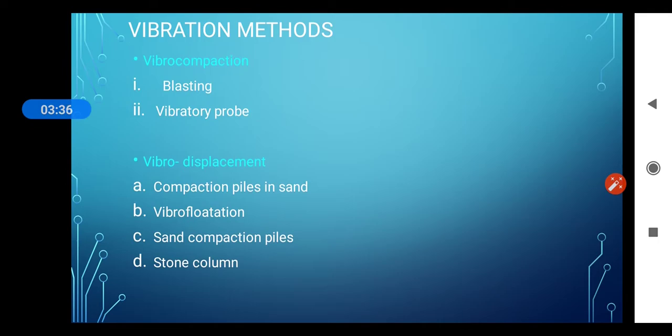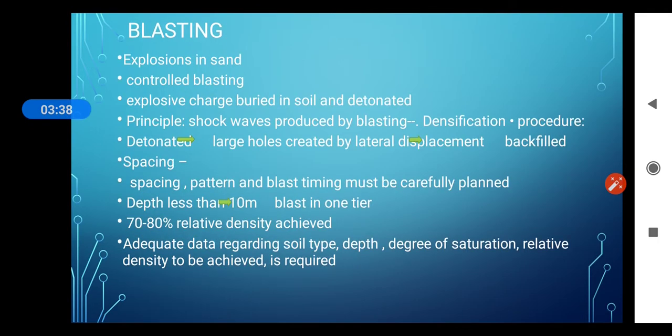Let us move towards the first one. What is blasting? In the blasting technique, a certain amount of explosive charge is buried at a certain depth in the cohesionless soil to be compacted and is then detonated. Due to the blasting, the shock waves produced cause the densification of the soil.